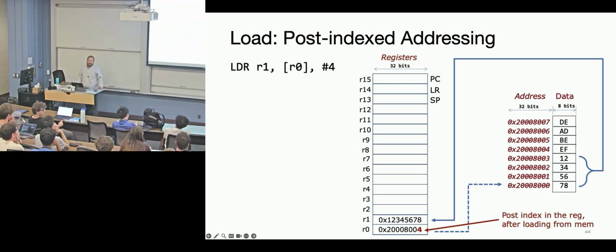One example is if you wanted to enable something for GPIO A and then you wanted to jump over right after and do B and then C, this will automatically do that for you. Usually we don't go across peripherals only because there's only so far you can jump at one moment. I think it's 256 plus or minus.